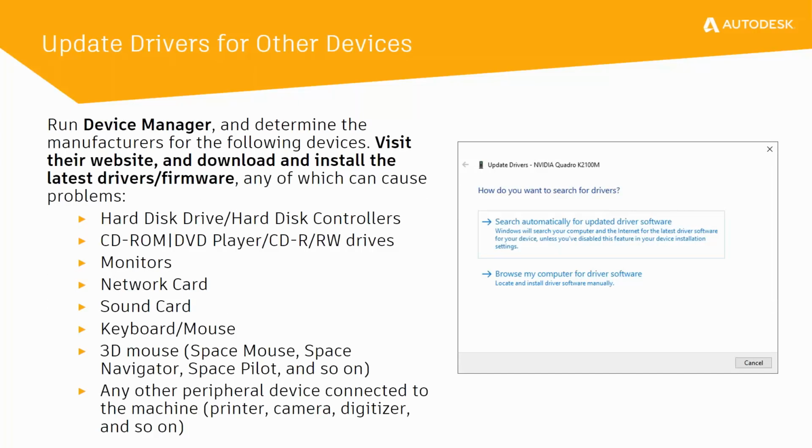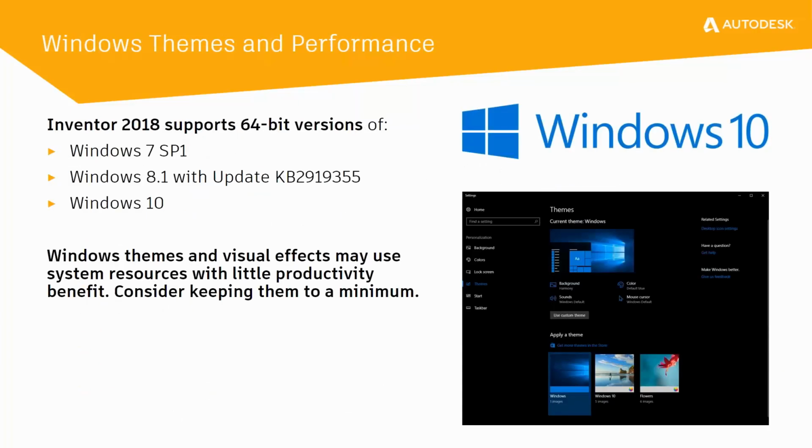The other thing you can do, whilst we're at it, is to update your drivers for other devices as well. When it comes to your hard disk drive or the controllers, whether it's the CD drives, which are probably less common nowadays, your monitors, your graphics card, your sound card, all of those sorts of things that you're using, make sure that the drivers are kept up to date, to help ensure that they're using the latest firmware and drivers available, and help minimize the chance that they're impacting the performance of working on large assemblies.